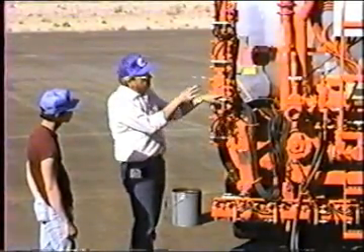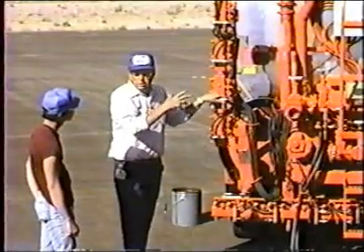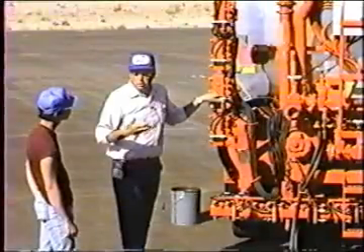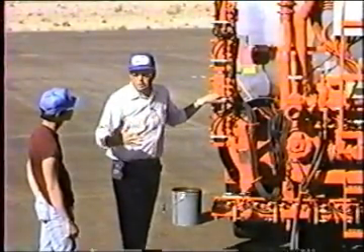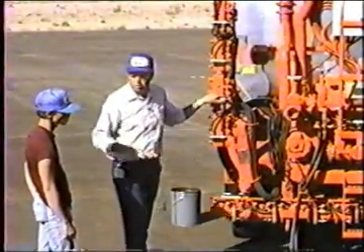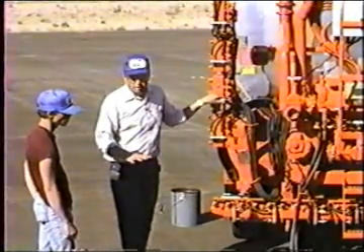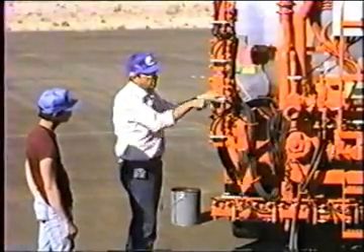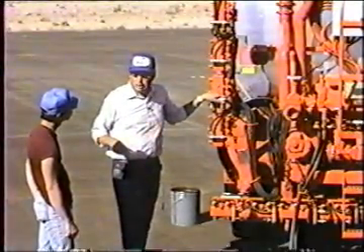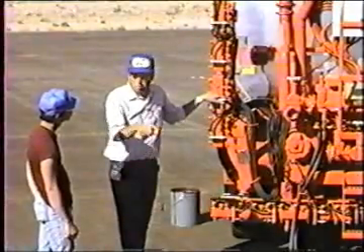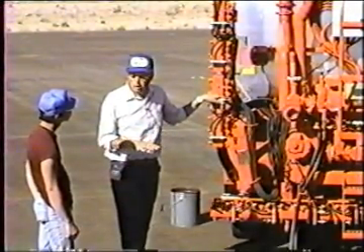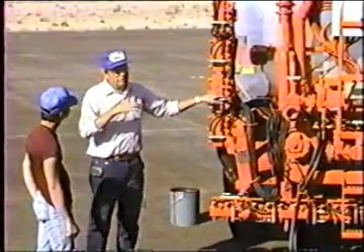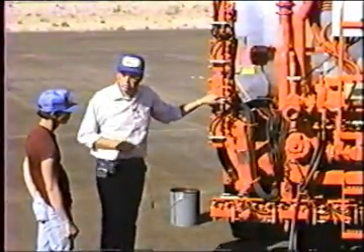The technical name for this thing is a liquid bituminous distributor. That means that it sprays liquid asphalt. Not only does it spray it, it distributes it. It evenly distributes it over every bit of the road that it covers. If you go to the job and the man says put down a quart, that means that he wants every square yard of this big piece of pavement covered with 1 quart or 1/4 of a gallon per square yard. We go through some elaborate things on this machine in order to have it put down that quart or 1/4 of a gallon per square yard.